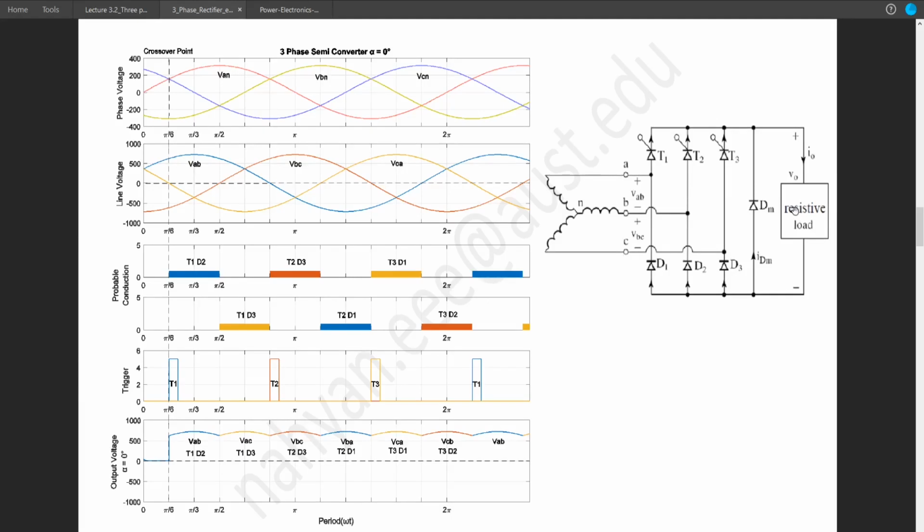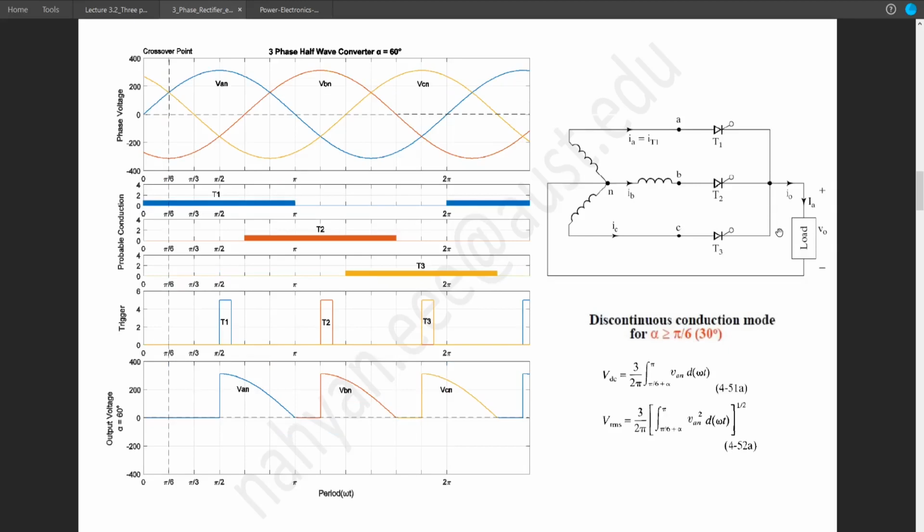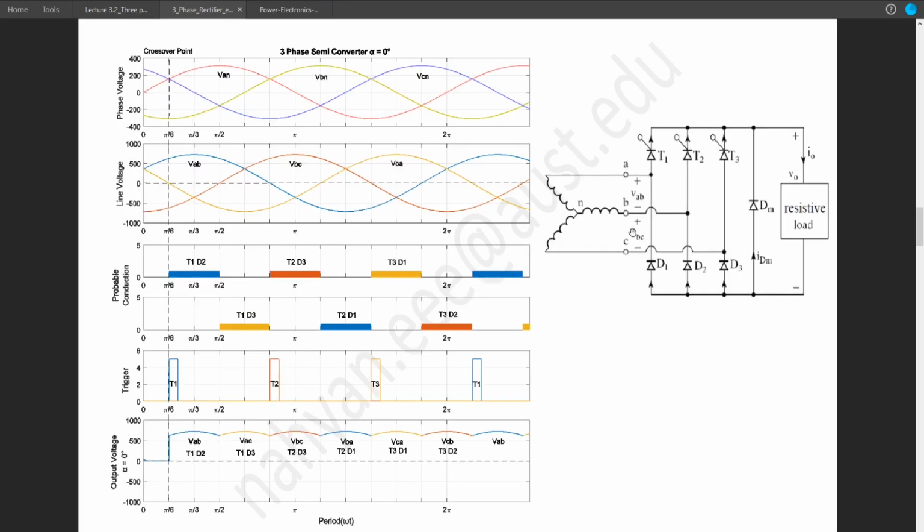And again, as the load isn't directly connected to this neutral portion, we will always get a maximum voltage which is equal to the line voltage. Unlike the previous circuit where the second terminal of the load is connected to the neutral, in this circuit no neutral connection is provided to the load. So the load voltage will always be equal to the line voltage. So we have to draw the line voltage diagram as well.